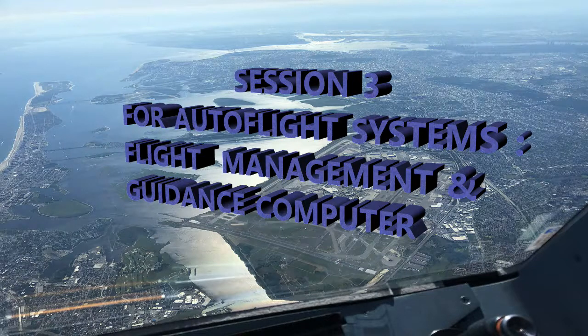You're going to see the letters LAT at the window. That'll be the lat window, to the right of the heading, and of course all that to the right of the speed window. The lat window is going to show a value in there when you have the heading or track mode active, or there's already a preset. If you have it pulled, then the heading or track mode is going to engage with the reference shown on the FCU. And of course it can also be turned, and it's going to show the effect of that. It's basically the same function as what I mentioned with the speed Mach control button and knob.